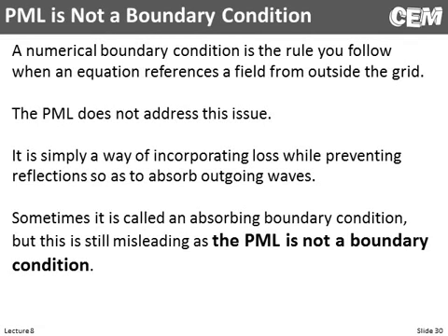The last thing I want to mention is the industry calls the PML a boundary condition, but make no mistake, it is not a boundary condition. It's not a numerical boundary condition or a physical boundary condition. The physical boundary condition being something like tangential fields continuous across the interface. This clearly is not a physical boundary condition.